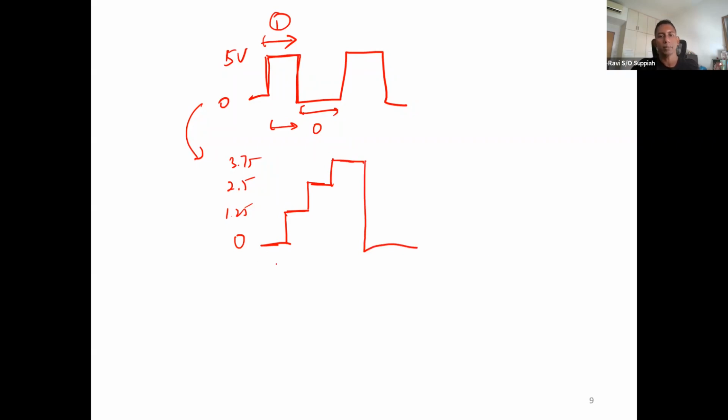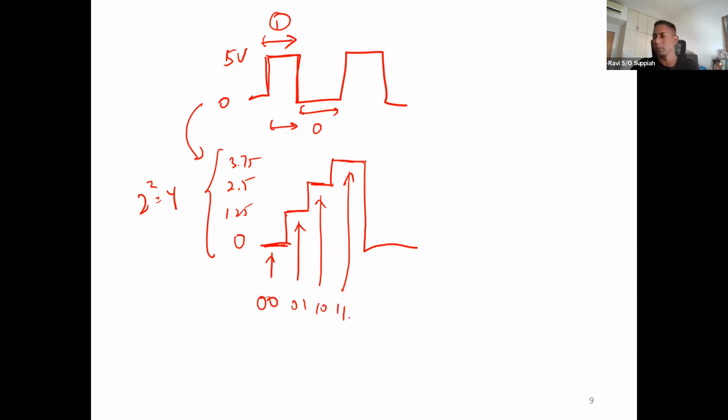Okay, so when I transmit one symbol, at each point of time, how many bits am I representing? Right now I have 4 different voltage levels, so 4 different symbols. So 2 to the power of 2 is 4. So when I transmit 0 0, it's equivalent to 2 bits. The symbol must be mapped back to the number of bits.